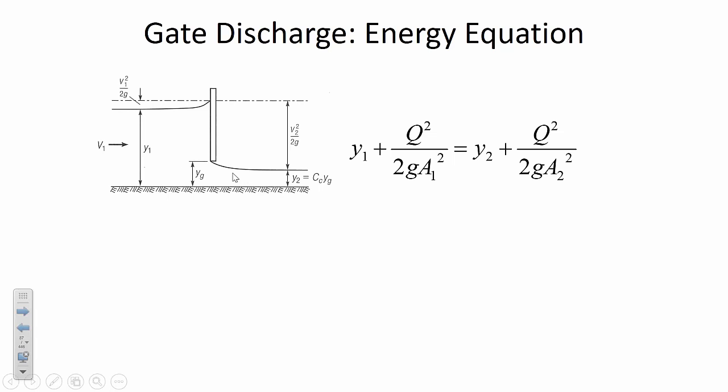The flow that's approaching the gate is greater than the flow that's going out under the gate. But then as the depth increases, so does the velocity of the discharge. Because if the depth is getting deeper, then there's more pressure pushing the water through that opening. And so that increased pressure leads to a higher velocity, and finally, Q equals VA in will equal Q equals VA out.